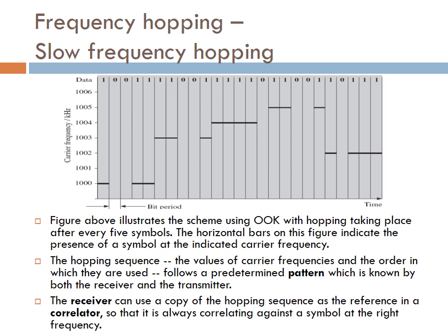Another advantage to frequency hopping, particularly relevant to military applications, is that frequency hopping signals are difficult to disrupt or jam. This is true of spread spectrum signals in general. The reason for this is that a conventional narrowband signal can be jammed by swamping the signal with a high power signal at the same frequency. To achieve the same effect on a frequency hop signal, the jamming signal has either to jam over the whole bandwidth used by the hopping sequence or else to follow the hopping sequence in synchronization.